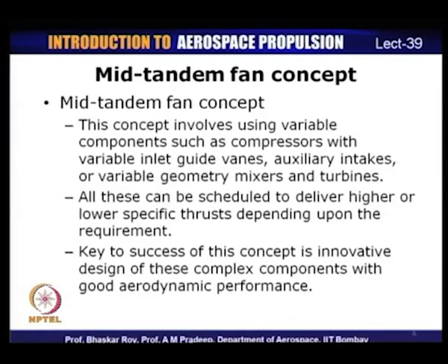So, let us take a look at the first concept, that is the mid tandem fan concept. Well, this concept will require using variable components like compressors with inlet guide vanes which are variable. It will require auxiliary intakes and variable geometry mixers and turbines and so on. So, there are a lot of complexities which are being introduced in order that the engine can operate in different modes. And so, all these complexities are basically meant to adjust the specific thrust to the required values.